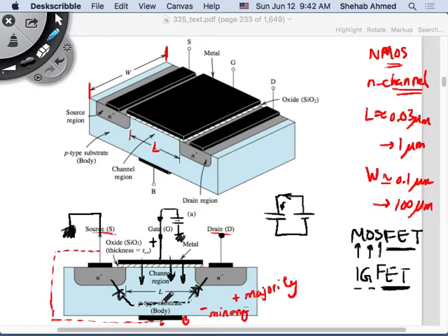It's like the infinite input impedance of the op-amp, right? Some current at the beginning just to bias it, if you want to call it that, and then it's not consuming any current, but it has a voltage across it. So there is a voltage at the gate with respect to the source. I can make this high or I can make it low. So it works very nicely as a control input signal, going into an infinite input impedance. It's a very nice characteristic that we get with the device.